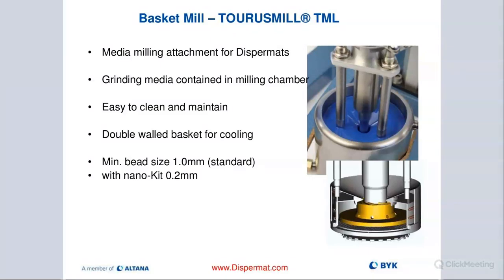And that basically allows us to really do a good job bringing down our aggregates down to the primary particle size. You can see the picture on the bottom right there is kind of a snapshot of a basket mill, what's inside. So inside of our basket mill, we actually have on top a pumping and steering system, which is kind of a wheel with some edges on top that will actually create a vortex.